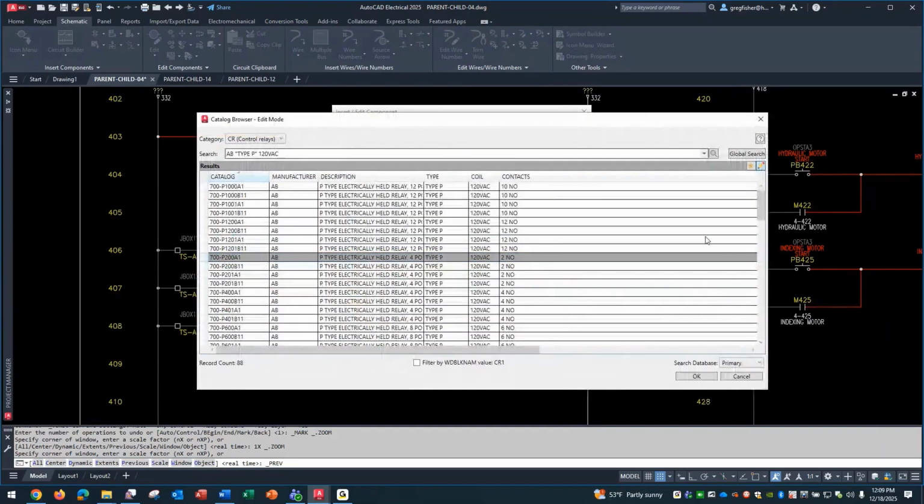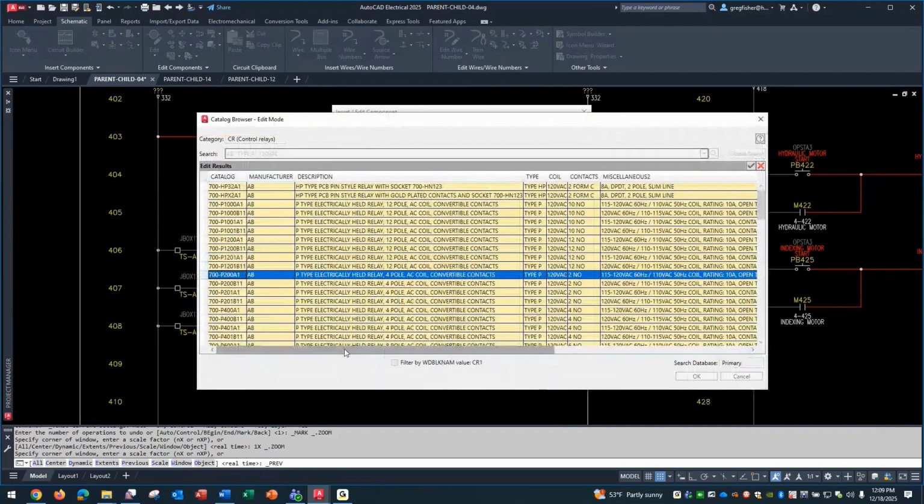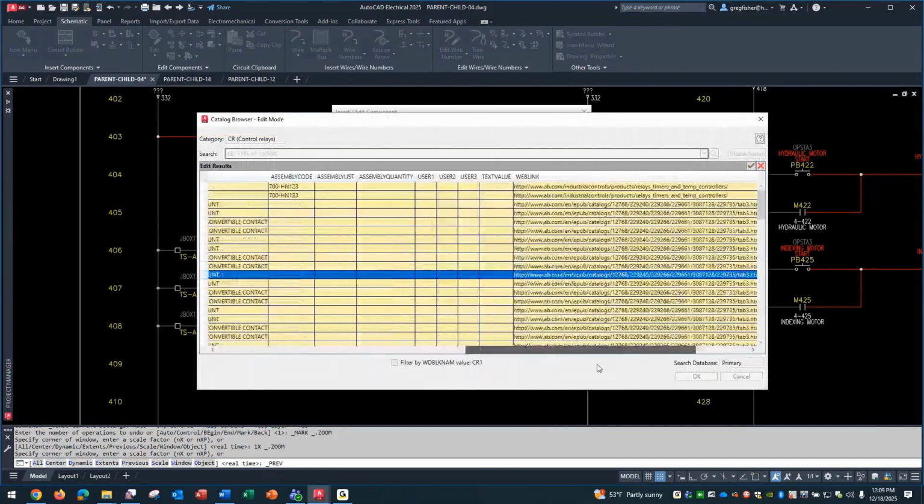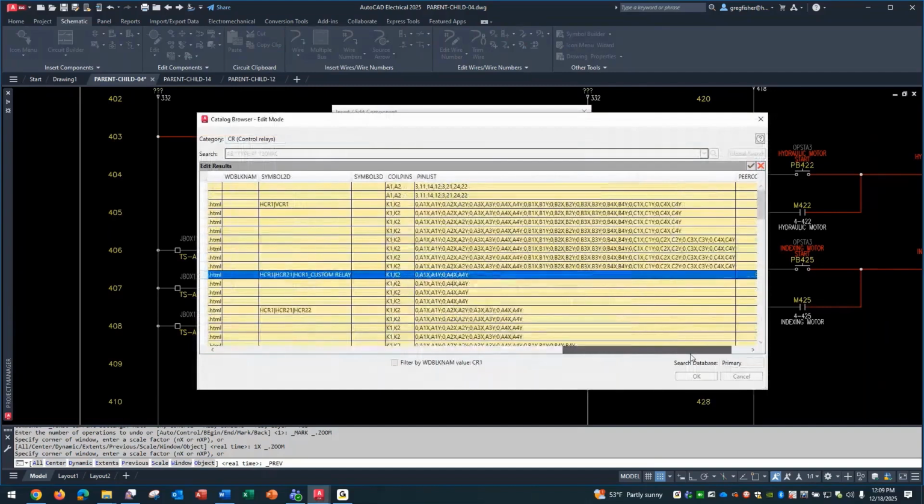So if I go to edit this, and this is where, when people first start using the software, and I go over this in class all the time, in the catalog number, to build that intelligence, to let it know that it's only, in this case, good for a 2-contact relay, we have 2 columns in the catalog number, one for coil pins and one for pin list. And this has always been a pet peeve of mine. I wish this column would be called parent pins, because not every parent symbol is a relay coil.